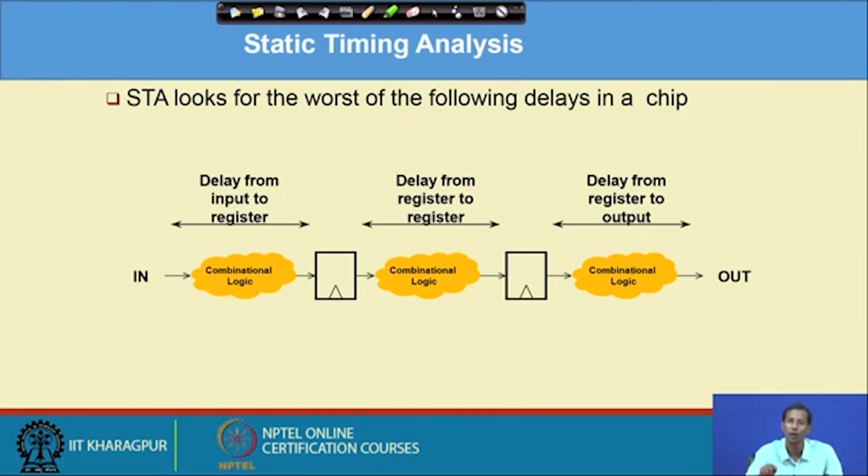So, it is dependent on the clock, not on the data. In a combinatorial circuit, if you change any signal, that will automatically reflect at the output. But in a sequential element, if you find the edge, then it will check the value present at the data, and based on that data the output will change.